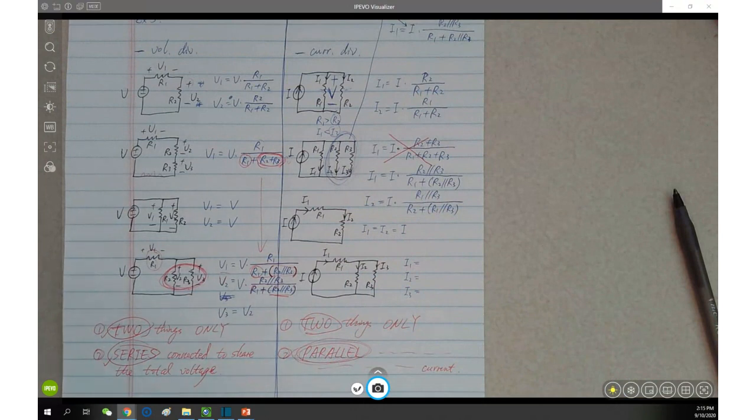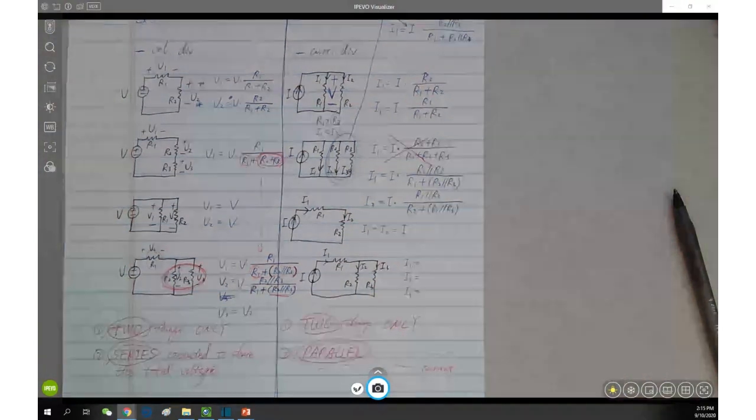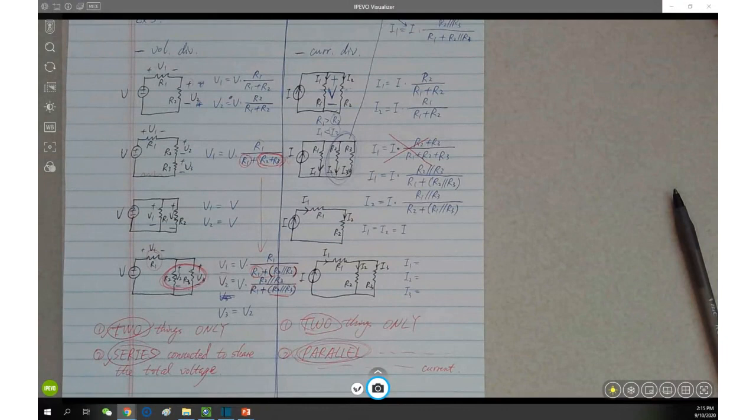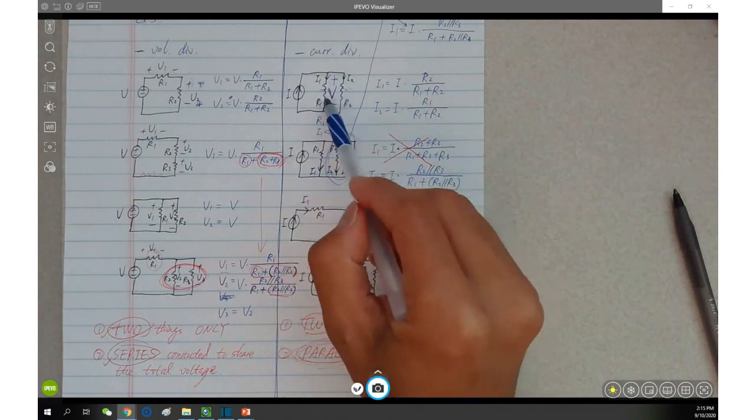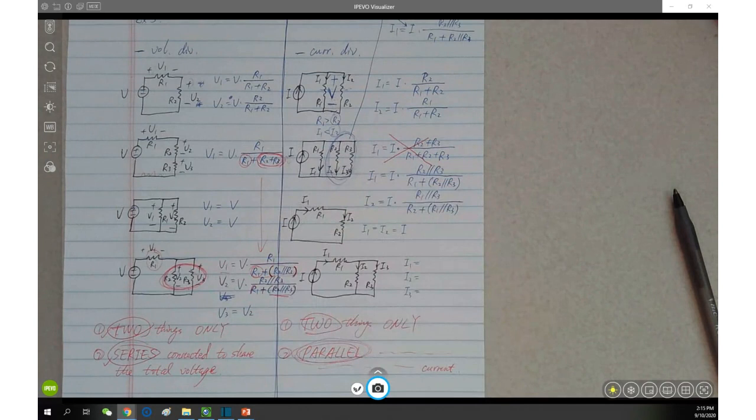The bigger resistor is going to result in a smaller current, and the smaller resistor in the denominator is going to result in the bigger current, because of Ohm's law. Once again, parallel, so same voltage, right? Does it make more sense now, Connor? And Kevin? I'm getting there. Maybe you guys are still working on this explanation, but by reviewing the recorded lecture, you can probably follow.